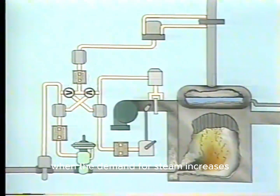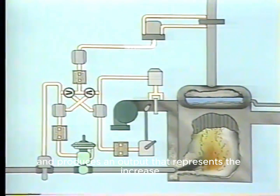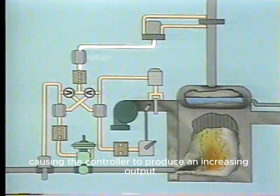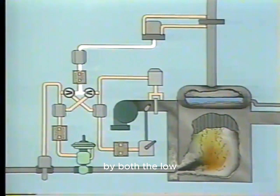When the demand for steam increases, the steam flow transmitter senses the increase and produces an output that represents the increase. This signal goes to the master controller, causing the controller to produce an increasing output. The increased output from the master controller is sensed by both the low select relay and the high select relay.